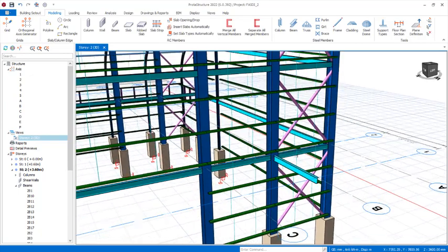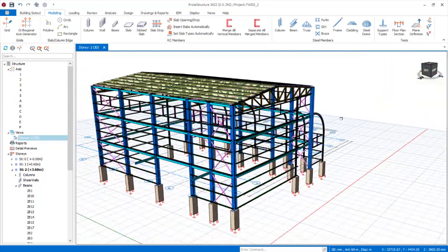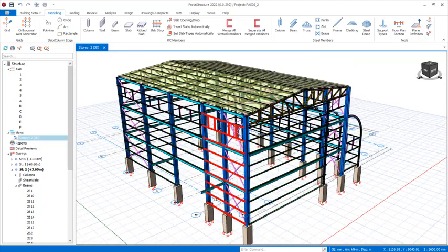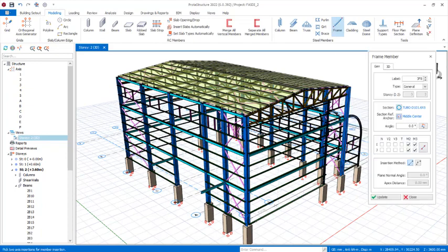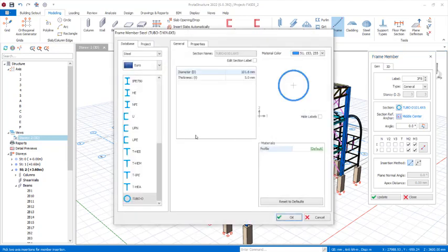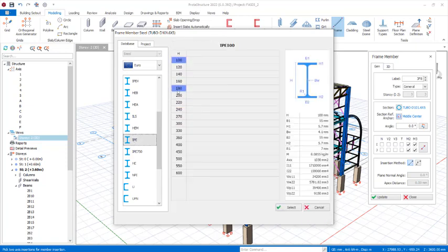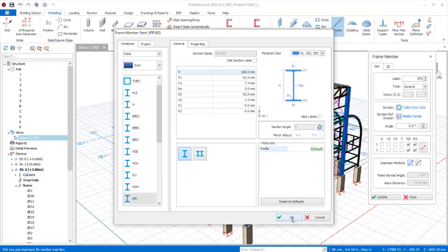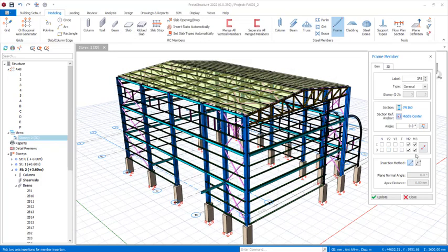We are going to be connecting a kind of curved beam like this that will connect this point and this point successfully. For us to do that, we will not necessarily make use of this property, but we will just click on these provisions, and we'll be using the same sections of the beams. Then we click on sections management, and then we navigate to the IPs. Okay, IP is this one. We'll be using this section 160. Click on this, select options, and then click on the OK options. So we are going to be inching both sides. I have these provisions checked very well.